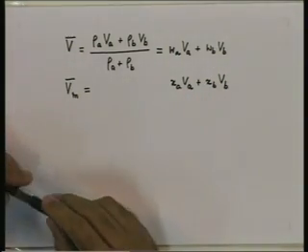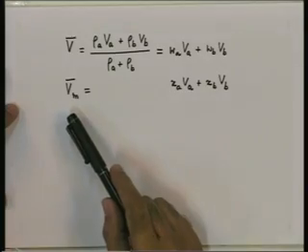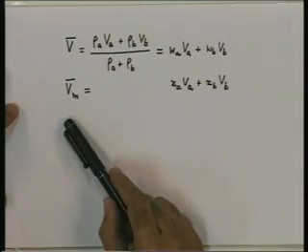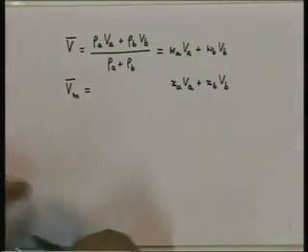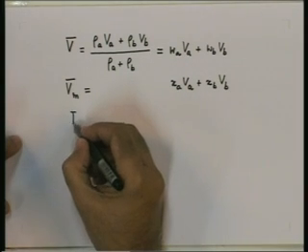In general, mass fractions are not equal to mole fractions, and hence there is no reason why in a general case the average velocity should equal the molar average velocity. So, in general these two average velocities will be different.